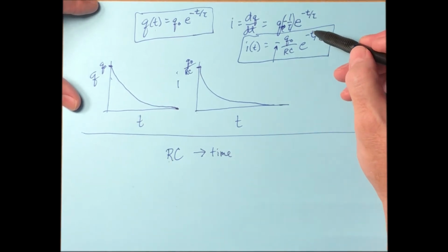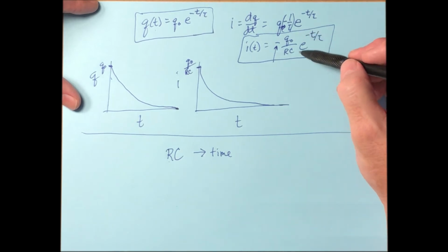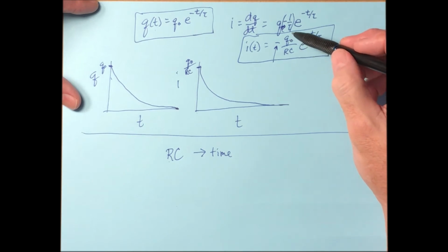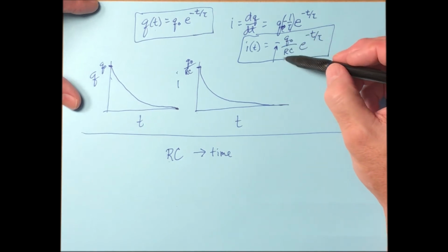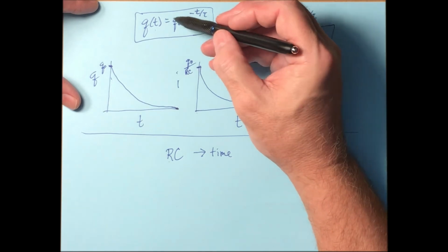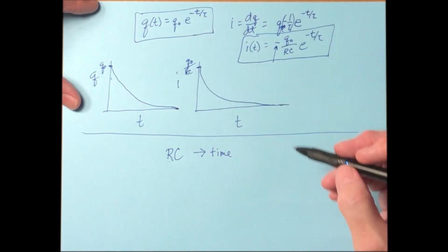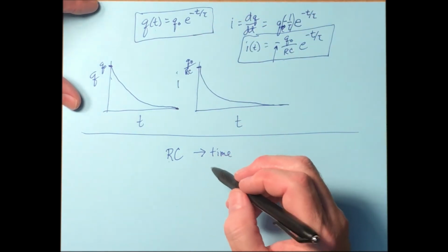You can tell that here because t on top is time, the bottom is also time. That means there's no unit associated with the exponential here. The exponential is the time varying portion of this function, whereas what's out front is the coefficient that tells you what the maximum value is. And that's true in both of these cases. The coefficient tells you the maximum value. But let's look at the unit here.